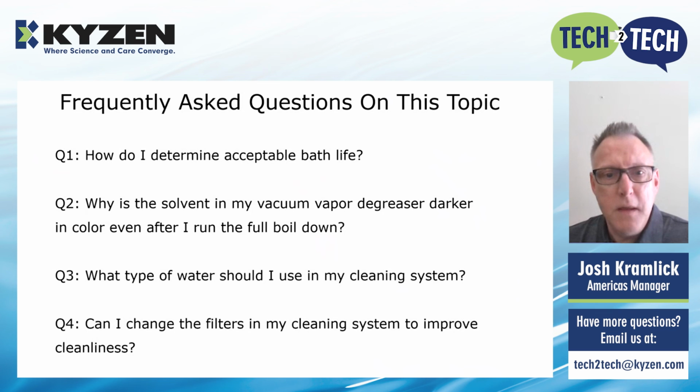Question 3, what type of water should I use in my cleaning system? Water quality is always a major concern. In most cases, we recommend using at least RO water to reduce the compounding agents that can interact with the soils and the chosen chemistry.